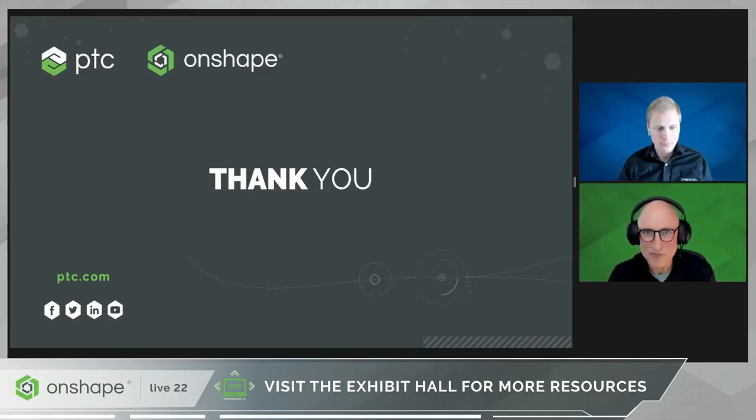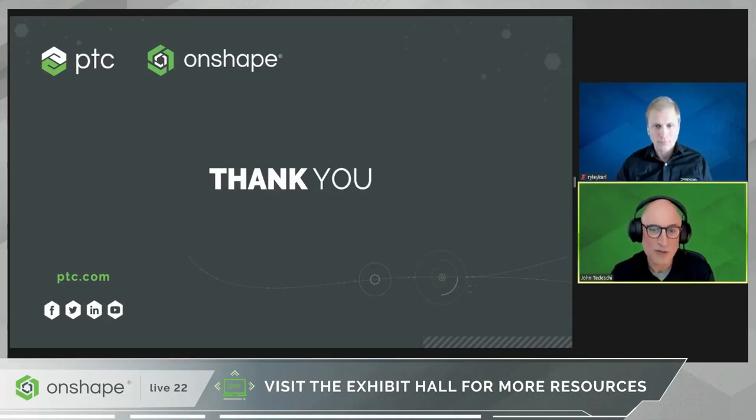Great. Can I use my own textures in Render Studio? Absolutely. You probably saw it at the first demo that I did, where I was manipulating the materials as they come in from Onshape. You select an object on the screen and go to the appearance tab on the right side, and you can see all of the characteristics of the material.